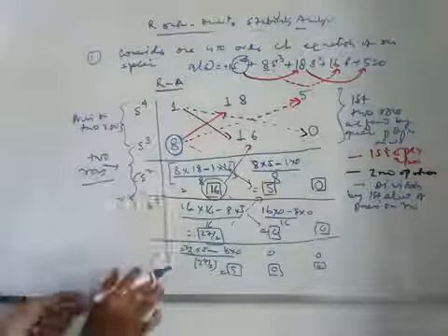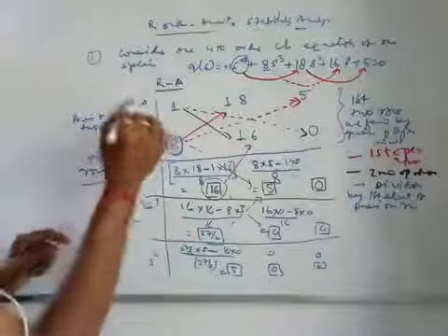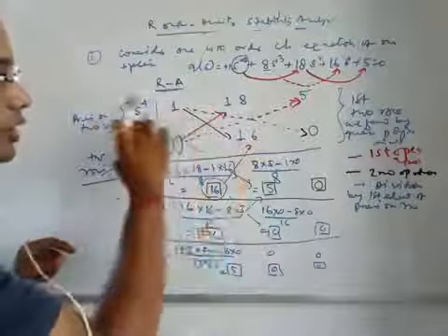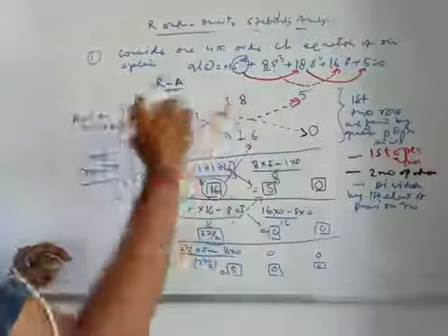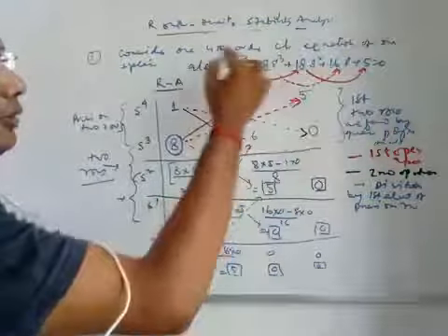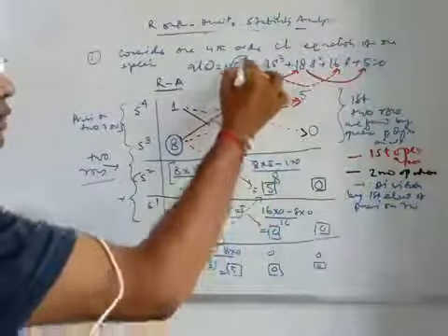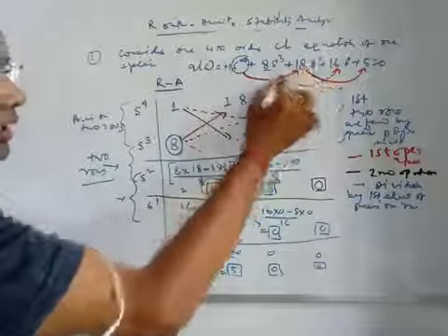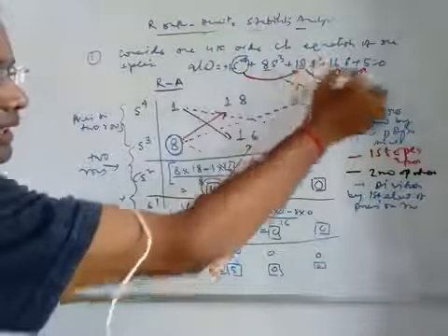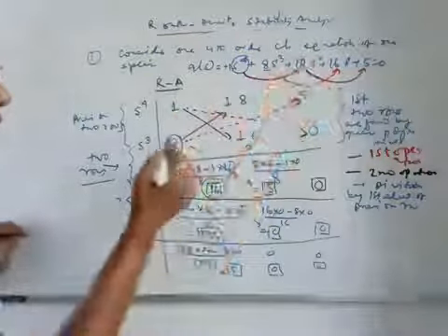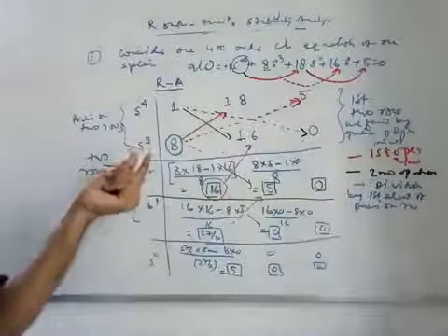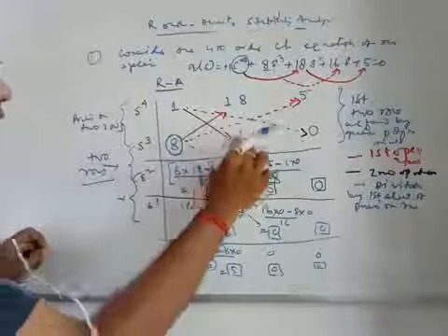You have to find out the coefficients of the row containing s to the power 4 from the given polynomial. That means s to the power 4 coefficient 1, you skip one term, that means the s square term coefficient 18, next 5. Similarly you form the array for s to the power 3, that is 8, 16 and 0.